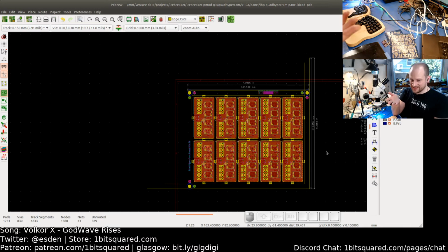This is something you should ask the OSH Park guys. There's a lot of variability. Four-layer boards need more shrinkage. If it comes to the panels for manufacturing at a CM for manufacturing boards in bulk, talk to your CM and let them do the panelization the way they need it for their machines, their pick and place machine, their stencil printer, for the best efficiency of manufacturing. Do they want flipped boards so that they can do just two runs of the same setup? There's a lot of variability. If you're doing it yourself, you have a pick and place machine, well, then it is up to you. And this is the case here.